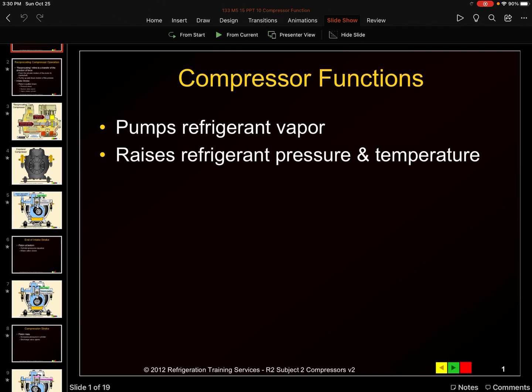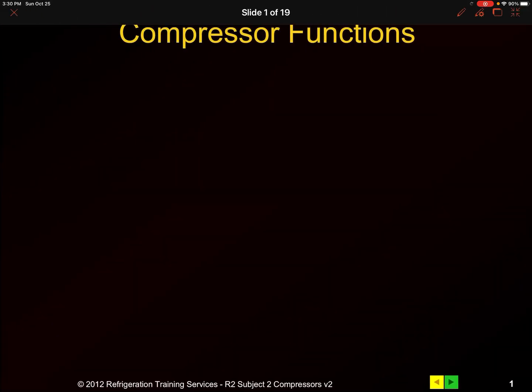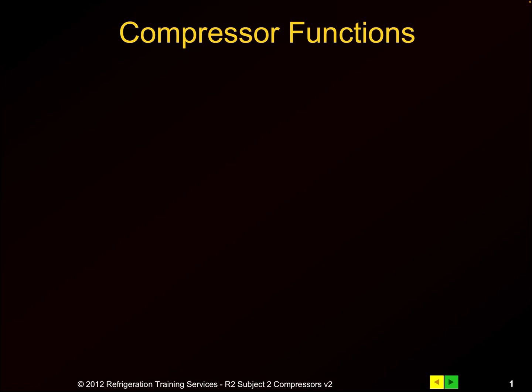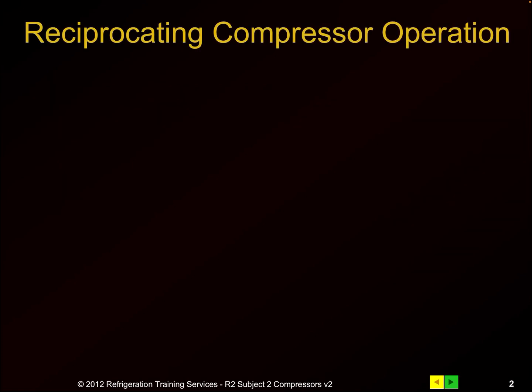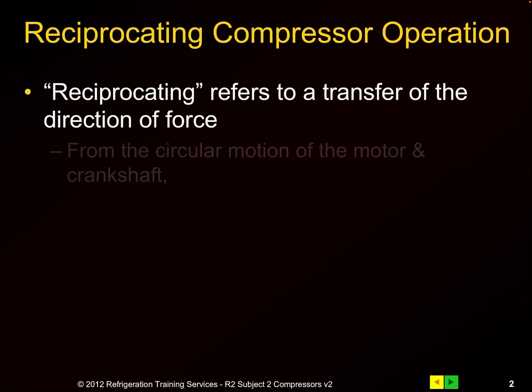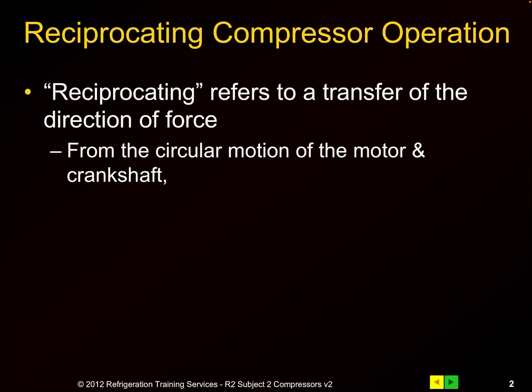So looking specifically at a compressor, one of the first things it has to do is pump refrigerant vapor, and it can only pump vapor. It does not have the ability to pump liquids. Its job is to raise the pressure and the temperature of the refrigerant. And those are two very important functions. So looking more at the operation.